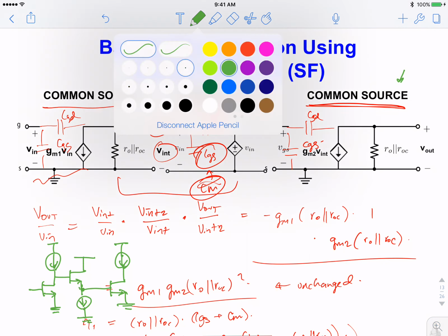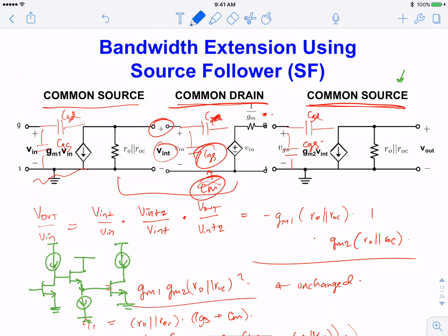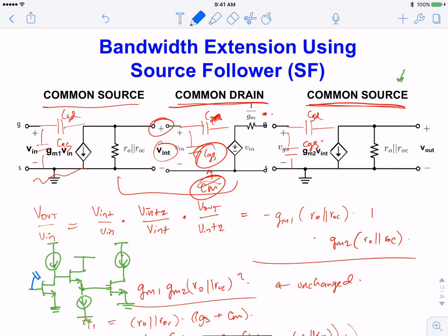This transistor has a Miller capacitance here, okay, but the input resistance can be very small. So the Miller RC, C is large, so this stage has a big C, but if you make sure your RS or Rin is small, then it's not a big problem, okay.